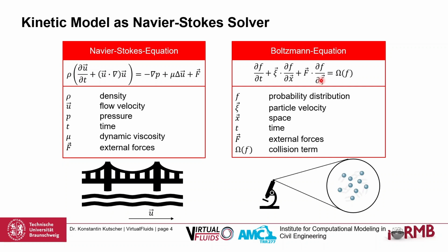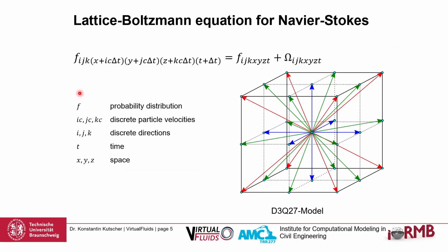But it's also a very complex equation. What is crazy is that we take this more complex equation, apply some discretization to solve another complex equation, and this is magic. Then we have this elegant formulation, the discrete lattice Boltzmann equation, for solving Navier-Stokes.